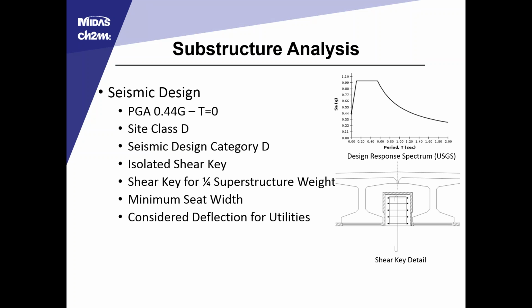The reason we can assume that the period is 0 is from the AASHTO LRFD guide spec, section 4.5. That assumption acknowledges the fact that the period of vibration is fairly difficult to calculate because of the interaction between the structure. And since the bridge is very stiff, we know the fundamental response will be short, so the approximation of 0 is appropriate. And we look at the shear key detail on the bottom right.